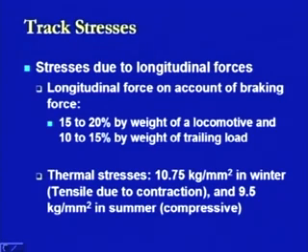In the case of winter, it is tensile due to contraction and the value is given as 10.75 kg per mm square, whereas in the case of summer, it is compressive in nature and the value is defined as 9.5 kg per mm square. So, what we found is that in the case of the longitudinal forces, the values range from 40% of the weight of the locomotives in the case of the tractive effort, 10 to 15 to 20% in the case of the longitudinal forces, and then there is a certain fixed amount of thermal stresses which are induced.